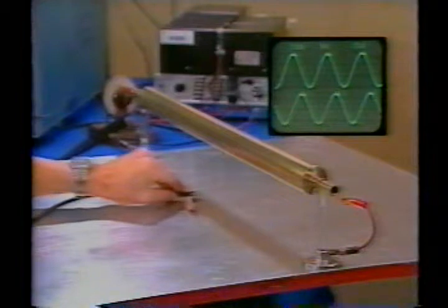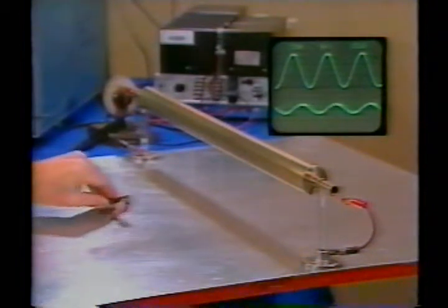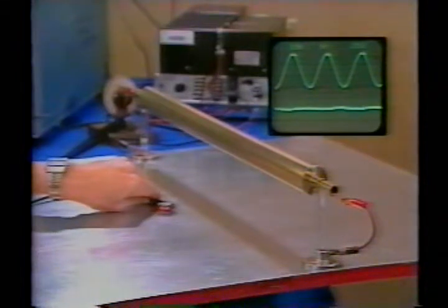Directly under the conductor, carrying a 3 amp peak current, as shown in the upper scope trace, we measure 9.5 millivolts peak on the lower trace. This corresponds to 0.11 Gauss peak. This is in better agreement with the theory than we have a right to expect, given such factors as the size of the sensing coil.